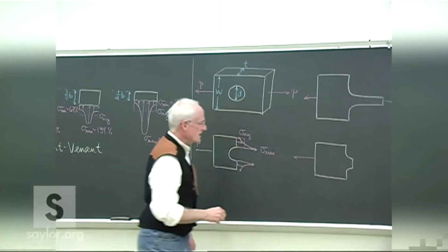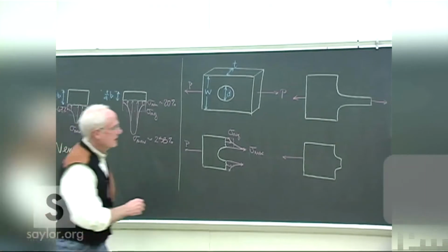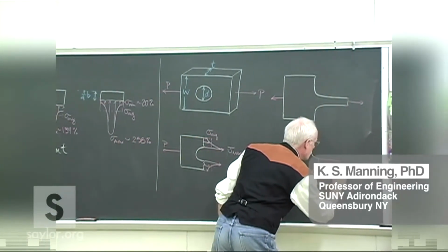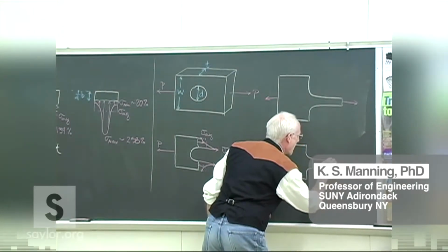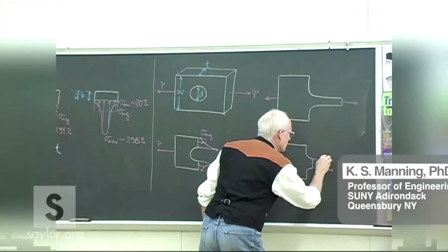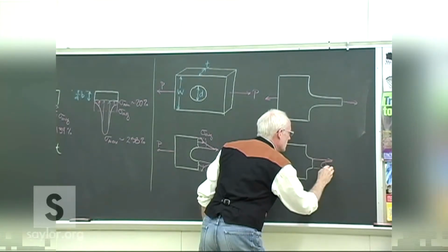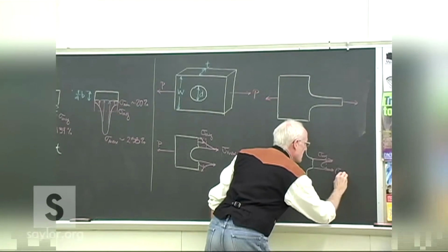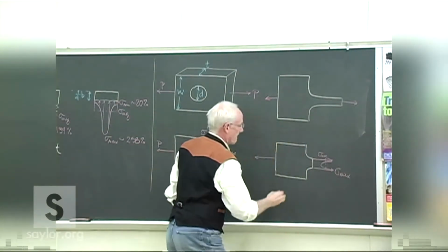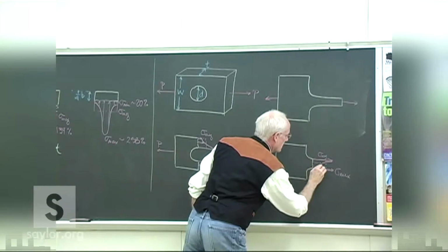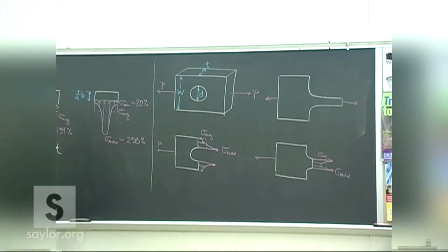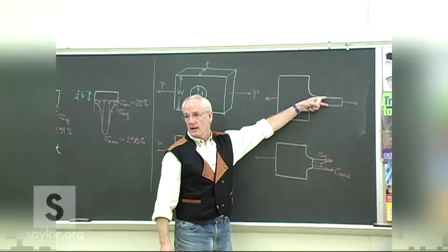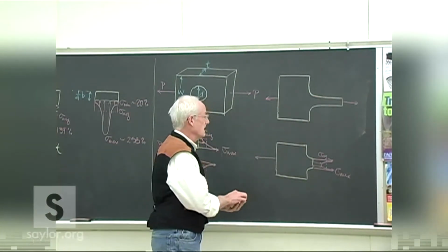So the actual stress distribution of that piece looks something like this, where the average we have been using is way back here. We now have these maximum stresses that we'd be underestimating, even if we use this minimum area, this much smaller area, to calculate the average stress.